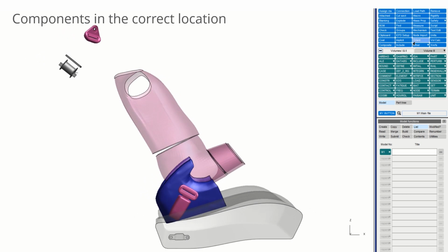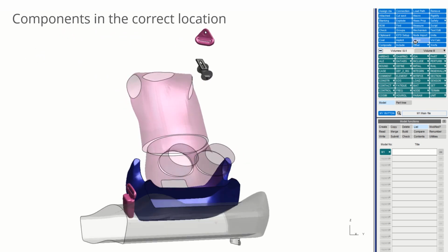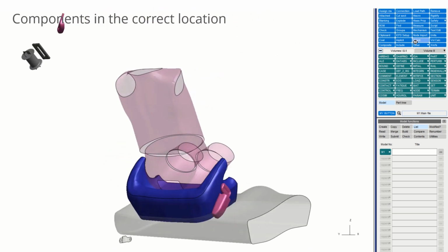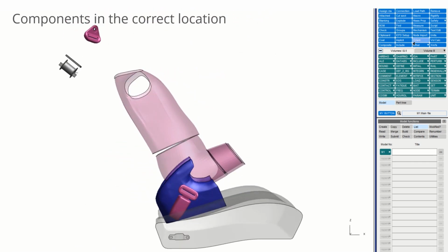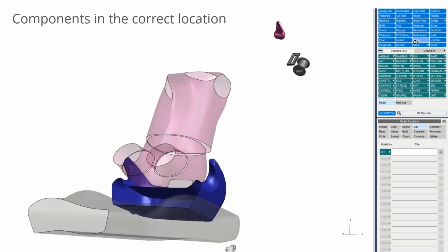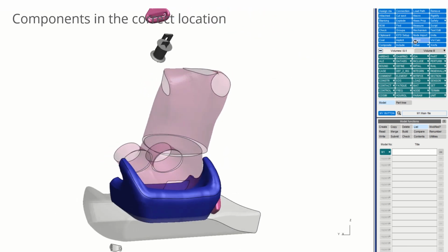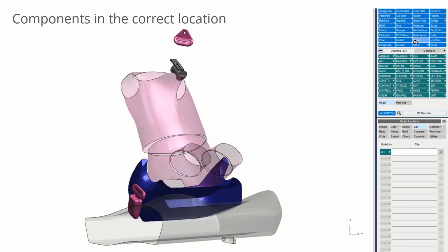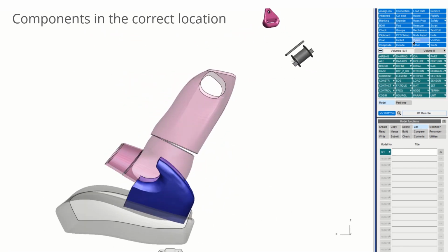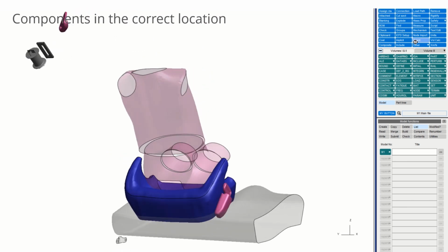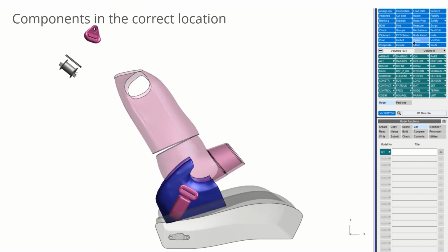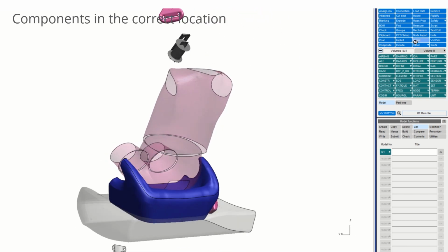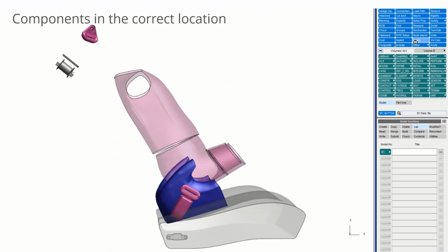The best way to get the correct location is to scan the parts in the real vehicle using a scanner attachment on a 3D measuring arm. If you don't have one of those, you could get good photos from all angles and use Primer's background image align tool to line them up and orient the parts into position. If you find the belt doesn't fit through the slots very well, it's likely you've got an unnatural angle with the slip ring, and try rotating them a little bit to make them more natural.